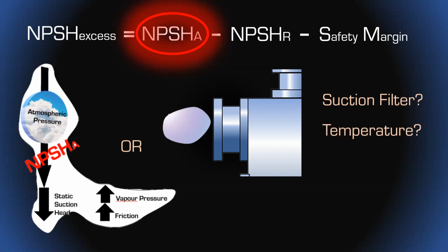Good. Temperature of the fluid. I'll answer this one, Chris. Temperature of the fluid obviously is going to affect the NPSH because the vapor pressure is built into that NPSH. So if I'm pumping water at 99 degrees Celsius, well, it's almost flashing already. I don't have to pull too much more vacuum on it to make it boil. Fluid, same idea. I could be pumping quite happily water at 40 degrees Celsius, but I now start pumping gasoline or something a little bit with a higher vapor pressure at the same temperature. That's going to give us some issues as far as the ease of vaporization.